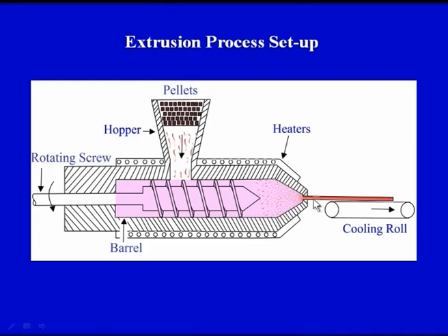So that is the forming process, and finally the cooling is taking place with the help of cooling rolls, and the heated plastic is getting the final shape, and the cooling process is taking place after that. So the three stages step by step are heating of the plastic pellets, or the raw material pellets are available in the solid form.